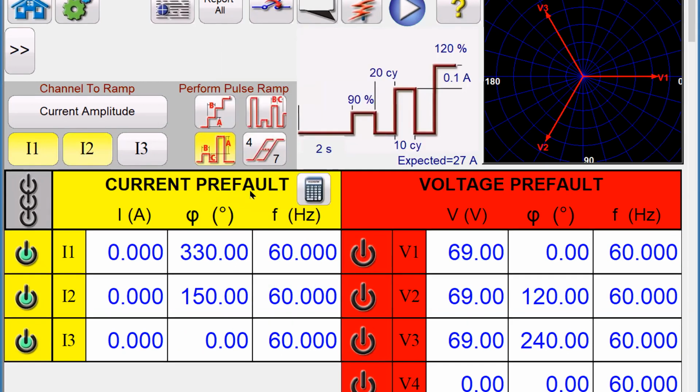I will show you the A to B. We're actually showing 2 currents here, A to B, 180 degrees out, and we're also doing the same parameters, right? Because the 50 element is the same whether I do 3-phase, single phase, or phase to phase values. And then now we need to know the expected value. This expected value is the setting that I pulled from the settings that you saw earlier. So now we're going to run this test.